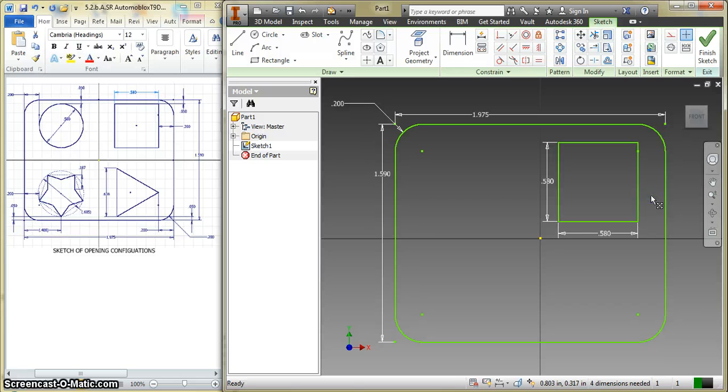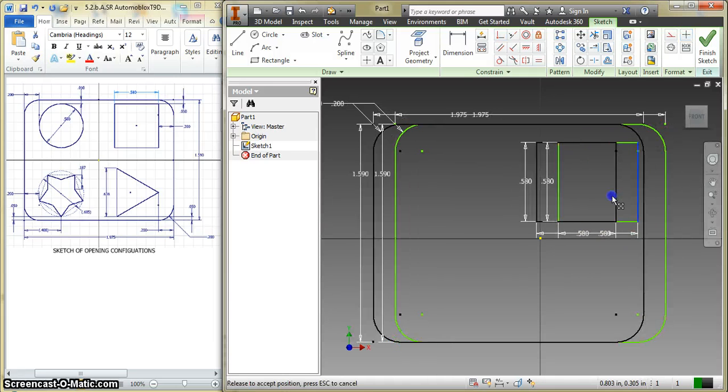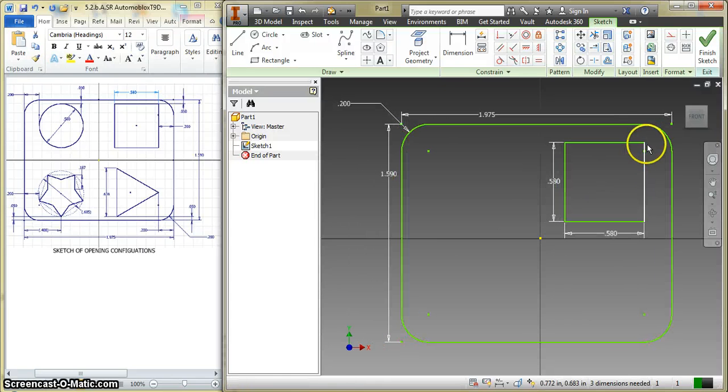So I'm going to delete this, and I can drag this over again. Do we see how this dot lines up with my line here? I can see that dot, which is the radius of my fillet, is lined up with that side of my square. So I can use my coincident constraint, which puts a point onto an arc. I can say this point I want to line up with this line. And now, if I escape out of that and try to drag it over, it will drag the entire sketch, because that point and that line are always going to be equal now. This can still move up and down because I didn't constrain it at all.